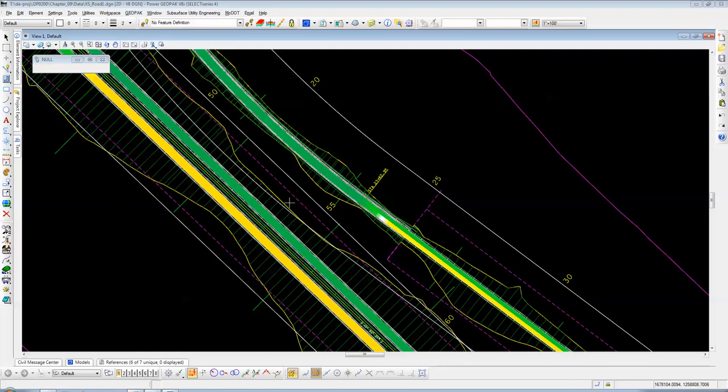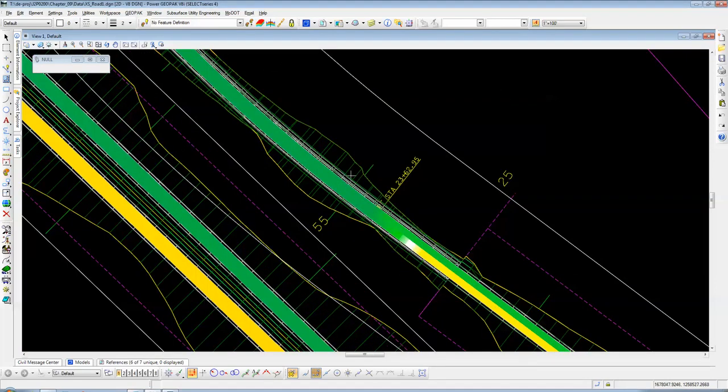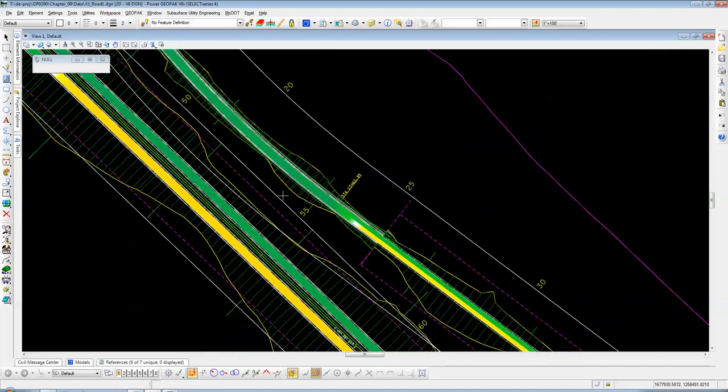Okay, in this video, I'm going to open up the Create Cross-Section tool and dissect all the parts that go along with it, and maybe hopefully give you a better understanding of what's going on. In this project I have behind here, the Road 1, Route 63 project that we've used for about everything these days, I'm going to take Road 1 and go through the tool and show you all the features with it.